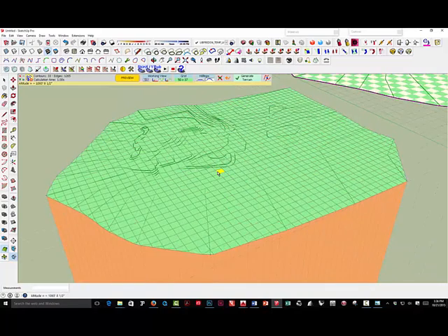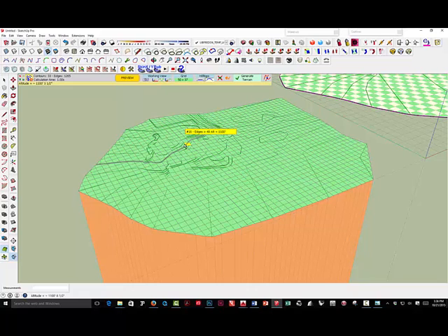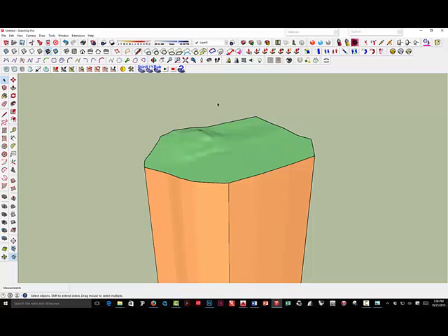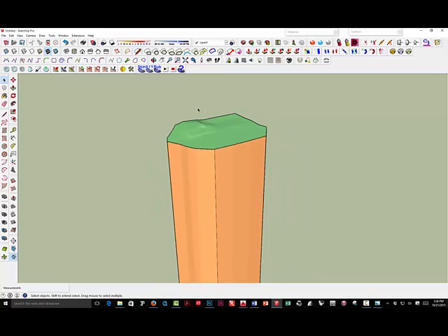And in this case, we don't really have to change the grid. It's accurate enough. It gives us pretty good representation. And so we'll just hit Generate Terrain. And then you move outside, click to exit, and it will leave the contour selected, which we'll just delete. I just hit the delete key.